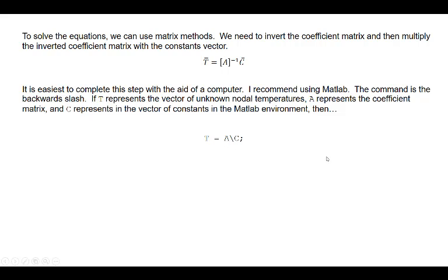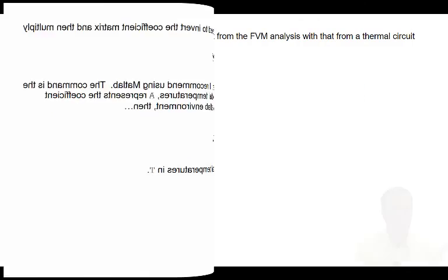The use of the backslash enables MATLAB to find the computationally most efficient method of inverting the matrix and solving for the unknown temperatures. This command will perform the calculations and store the result for the nodal temperatures in T.